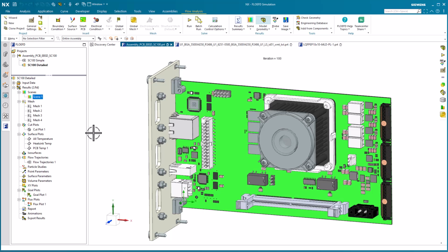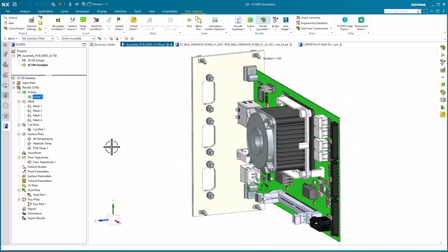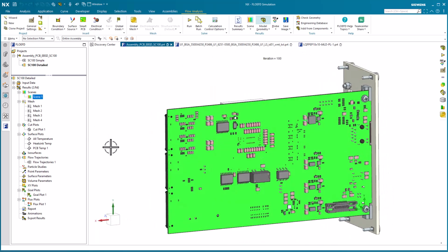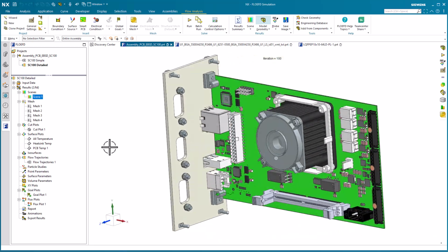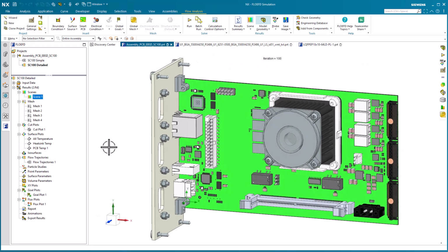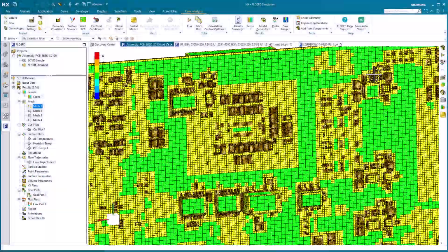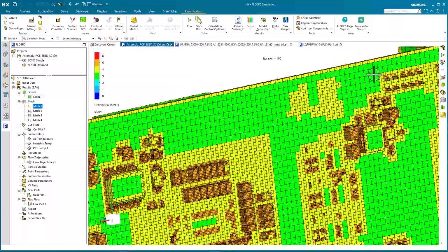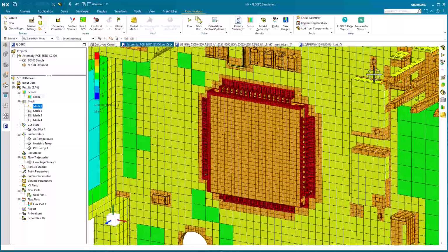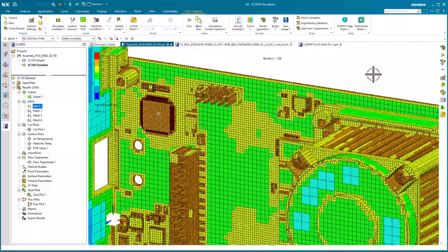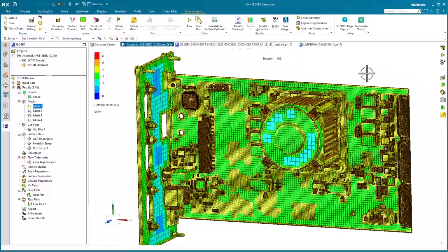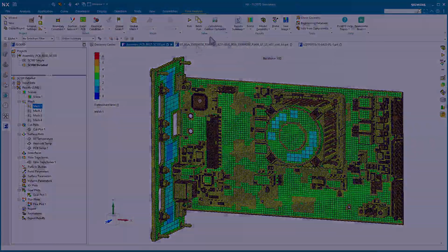Okay, now we've looked at the simplified model, let's bring back all the suppressed components for a late-stage validation simulation. The FlowEFD project doesn't have to be scrapped and restarted. The project clone command is all that's needed. The mesher is run again, and we can see the vastly more complex mesh now. The maximum refinement level is still 6 with the finer mesh on the LQFP.